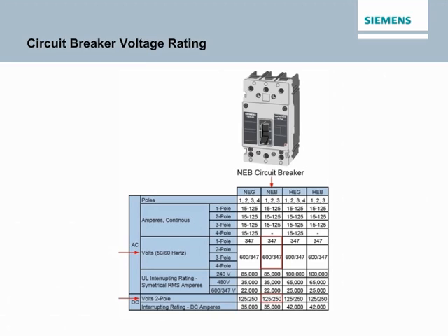In such cases, the breaker may be applied in a circuit where the nominal voltage between any conductor and ground does not exceed the lower rating, and the nominal voltage between conductors does not exceed the higher rating.